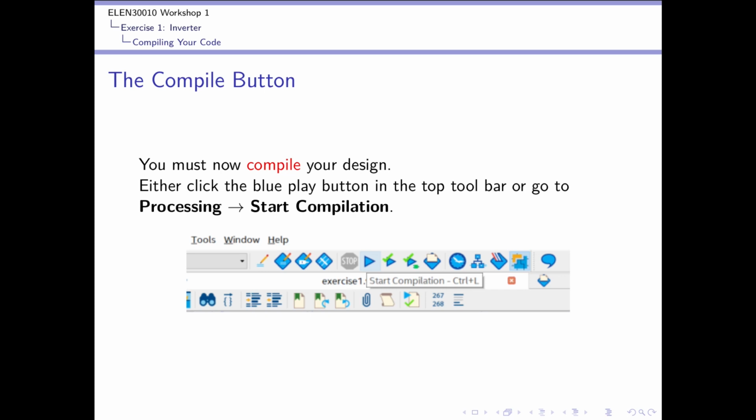on that PCB. A similar process occurs with the FPGA, in that this design has to end up on the FPGA. Now, inside the FPGA, as we will learn later, there are a whole bunch of logic gates, or technically lookup tables, and we have a case of the software has to work out which ones to use, and how to flick all the switches inside there to wire up the logic gates in the correct way.